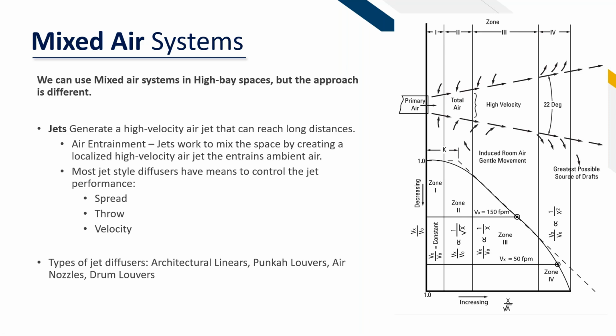So these can be very high throws. We can throw these across the room pretty effectively. And there are also some damper styles on the back that we can actually utilize to throttle these down up to 50% in some cases. So in a lot of cases with jet nozzles, there can be a concern with noise. But in a situation like that airport terminal, we're not as concerned with noise. So jet nozzles would be a great approach there.